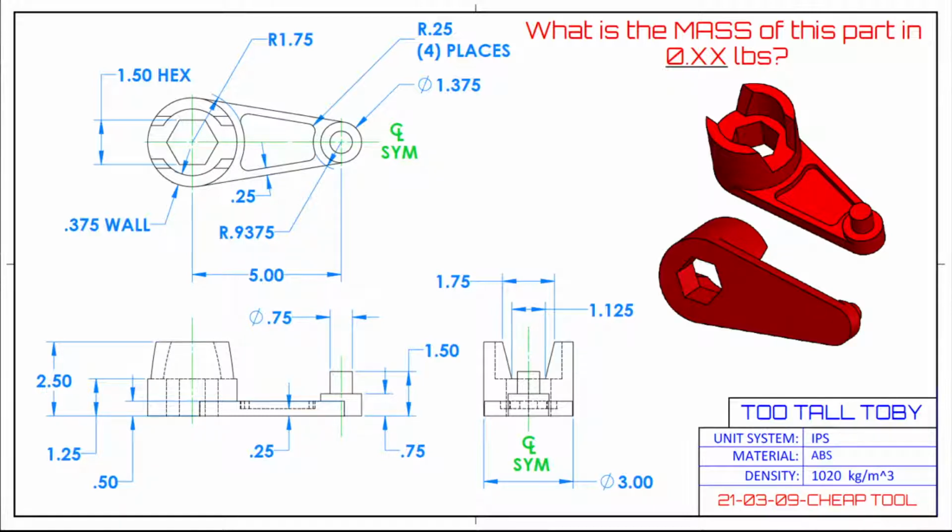In this case, there's a pocket. Is there anything going on with that pocket that I should know? I mean, it looks like the radius is coming from the center point of the 2 circles. It looks like the sidewall is offset by 0.25. Is it possible that radius at 0.9375 radius is also offset by 0.25? Does that work out? If I take 1.375 and I divide it in half and then I add 0.25, does that get me to 0.9375?